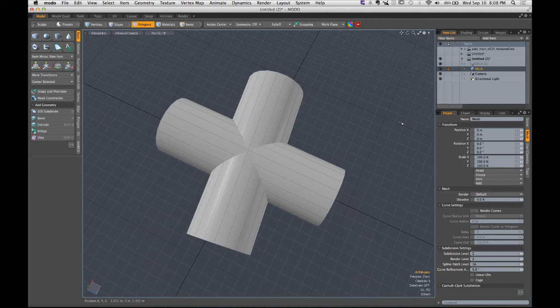If you rotate it at an unknown axis, let's say you rotate it 10 degrees, you drop the tool, you walk away from it for a couple steps, then you want to rotate it back. Well, if you don't know which value you rotated that cube on, the computer's not going to know, and the computer's not going to auto-snap it back to the origin of the scene. Unfortunately, the solution to this is rebuilding that shape. It'd be faster to rebuild it than to try to figure out the angles and make it look perfect. Can you demonstrate that?